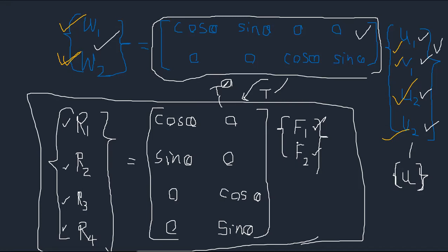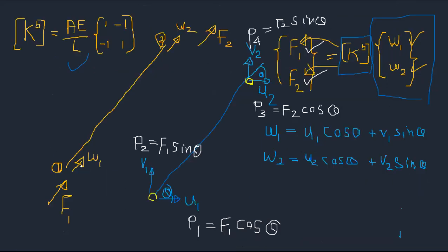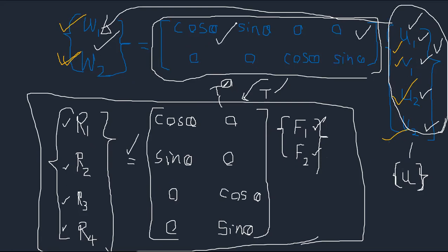what we need to do is actually, so this P1, right, and R1 and F1, there's some relationship, but when you determine the nodal displacement, you can determine directly the axial displacements along the joints, right? W1, W2, if you know U1, V1, because we have already determined this, right? So it's just a matter of plugging into the transformation, right?